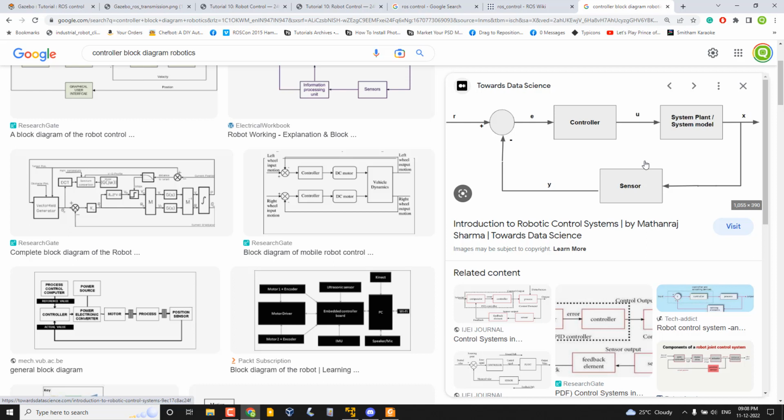if you want to move a joint to some degree, 90 degree or something, you are giving the 90 degree to a set point. Okay, that is actually the set point or the goal point, and you are giving that not directly to the motor, but through a controller.